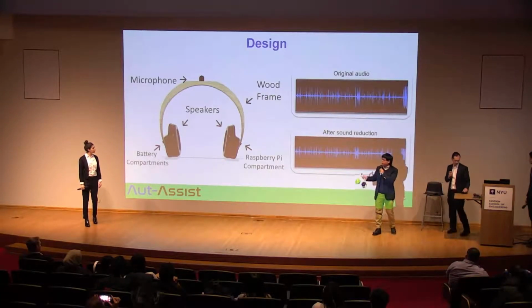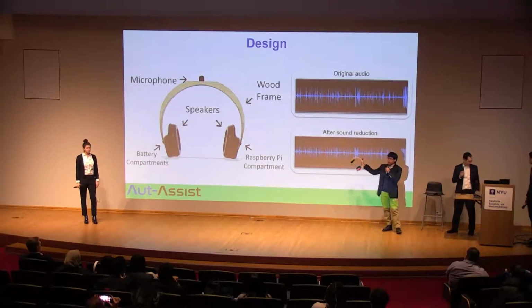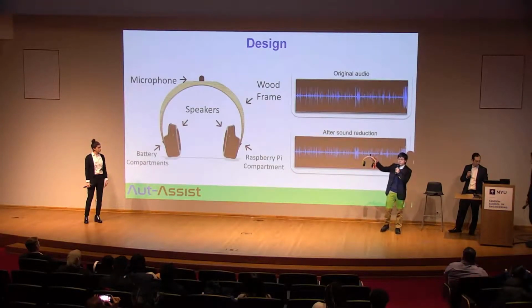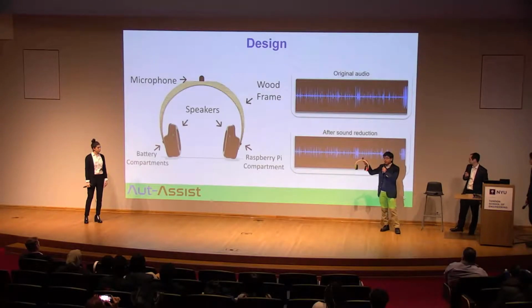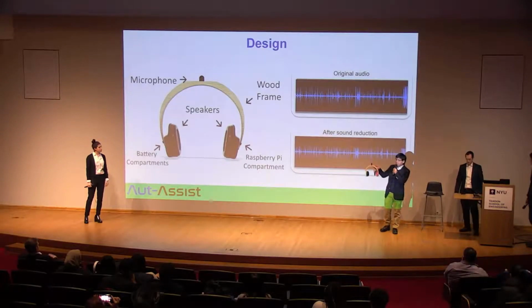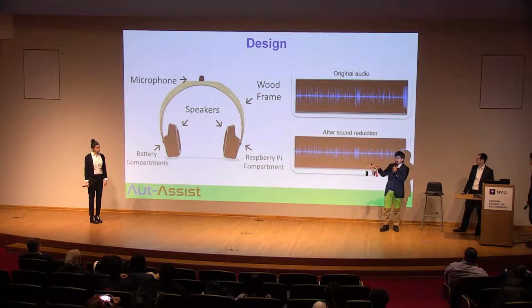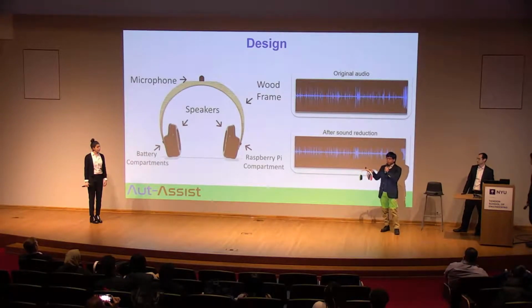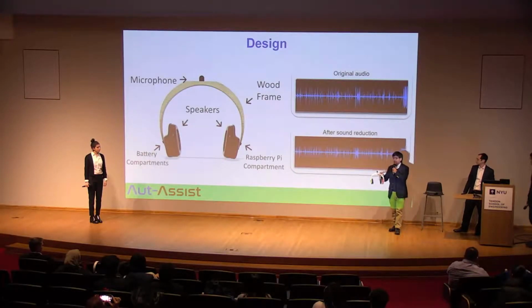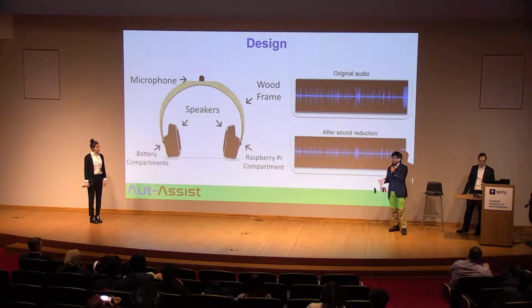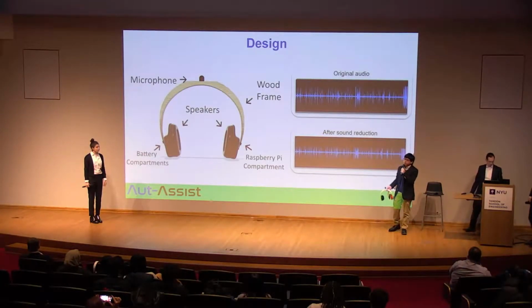Thank you, Daniel. I'll be introducing what our product is and how it works. As you can see, the SmartStance has 5 components, the 2 highlights being the outer frame, which is built from wood using laser cutting, and the processor, a Raspberry Pi. The Pi reduces noise by performing A-weighting and L filtering. For those of you who don't know, L filtering basically smooths out the sound, and A-weighting transforms the noise sound waves into frequencies the human ears understand, that is, decibel levels. The Raspberry Pi also picks up information from the server, so the user can update the preset decibel level through the app.